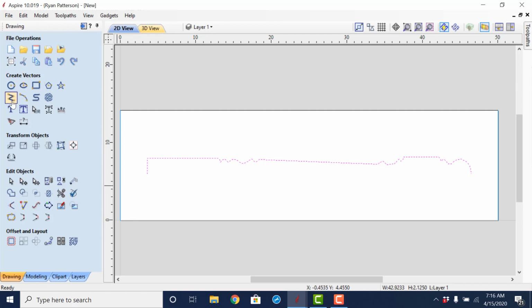Should also mention with the two-rail sweep, we don't have to have the cross-section scale to be exactly what the object is. It will automatically stretch out and scale according to the distance of the two rails. But in this case, I did draw it out to scale of what we want our cross-section to be. Again, it helps to visualize exactly what we're getting, and we know exactly how it's going to end up.